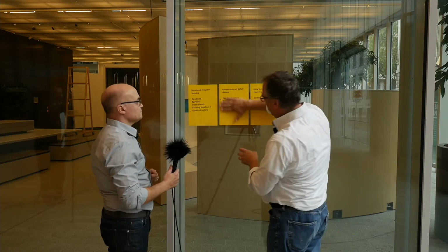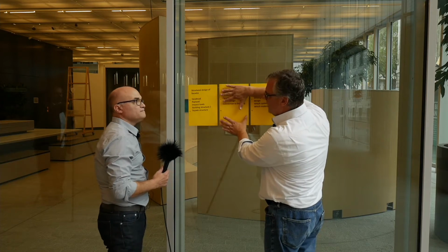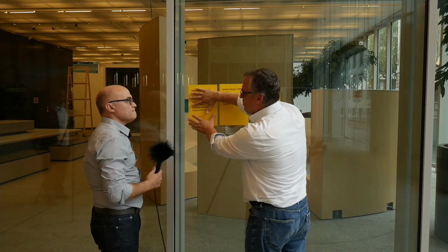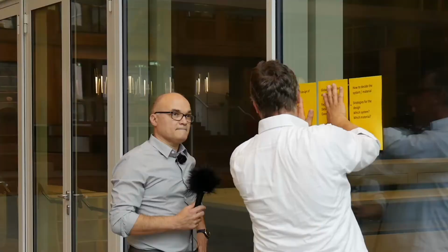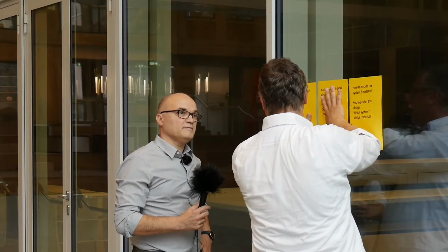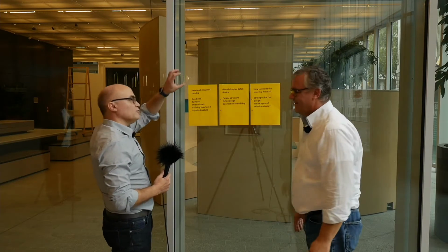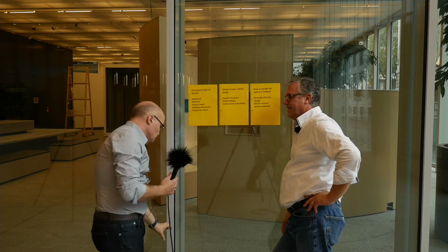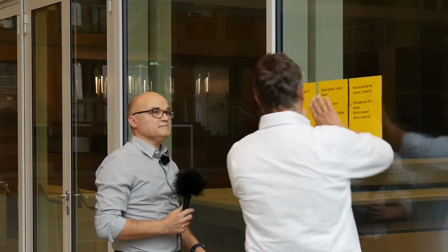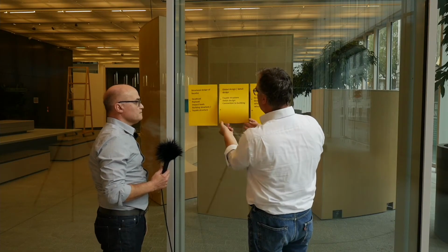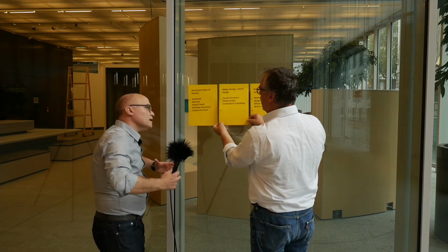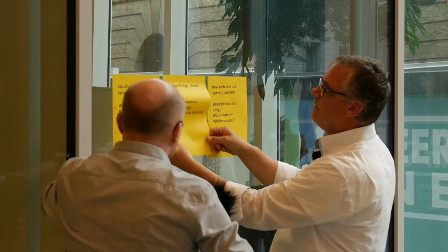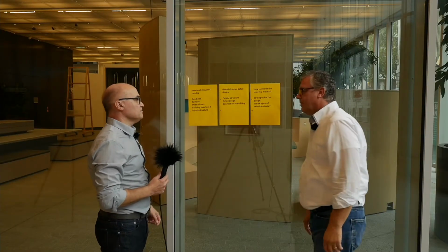Okay, so we have one which is moving versus the next one which is moving, so we have to make sure that they don't touch each other. Correct. So you connect one end, for example the top, so it cannot move in three directions, whereas the bottom end will only be connected laterally. Laterally, so out of plane. So this is fixed here and it's kind of loose here. Correct. So it can expand and contract without stressing each other. Okay. Good.